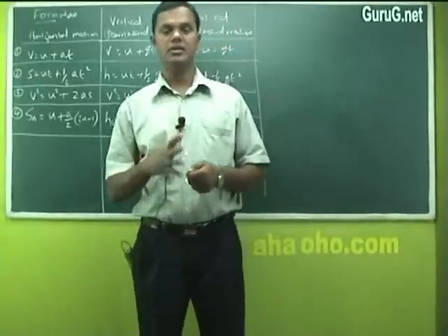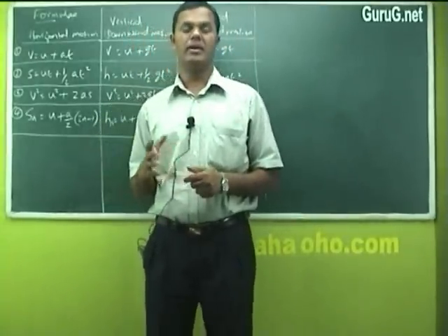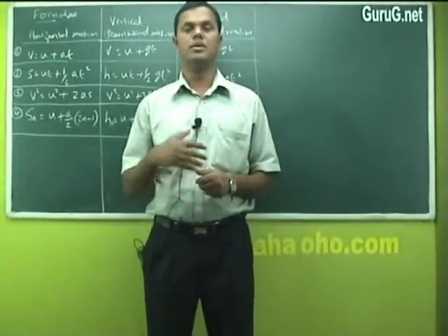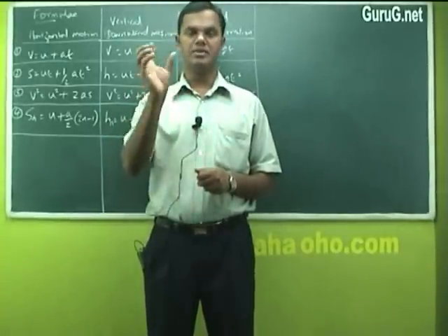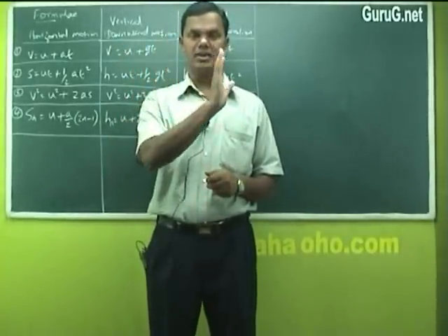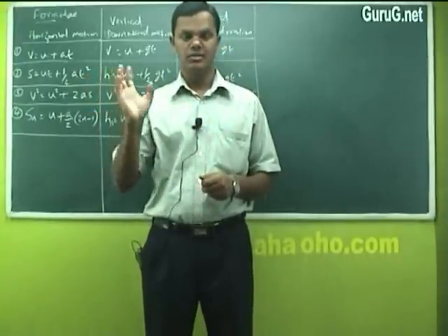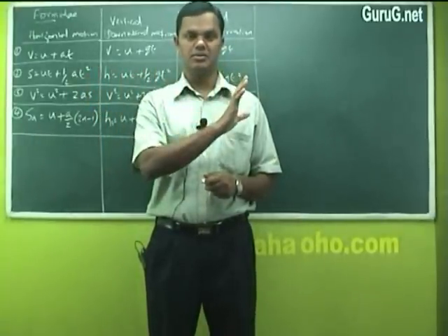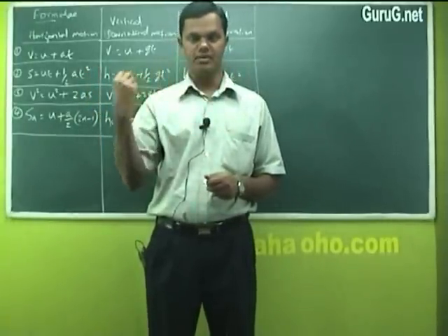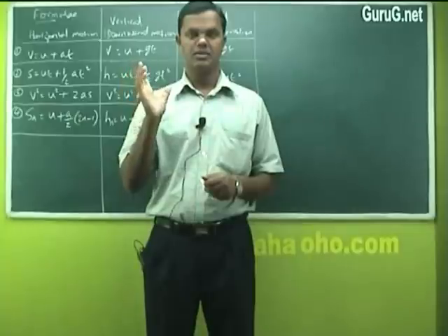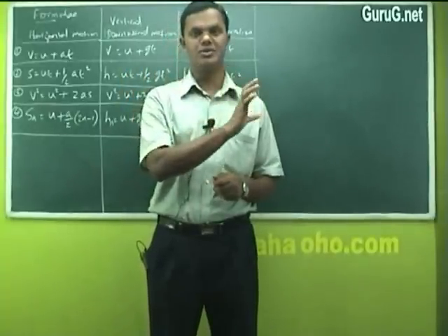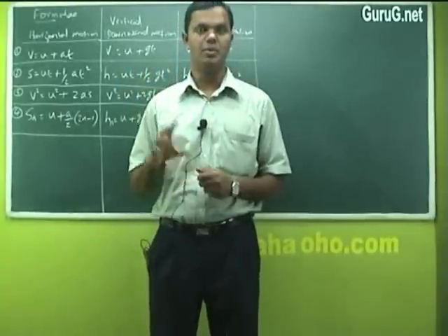So we have seen the basics of dynamics of particles. Let me recall what we have gone through. Dynamics is divided into two main subdivisions: kinematics and kinetics. Kinematics is based on the analysis of velocity, acceleration and displacement, but without considering the force actually acting on any body.